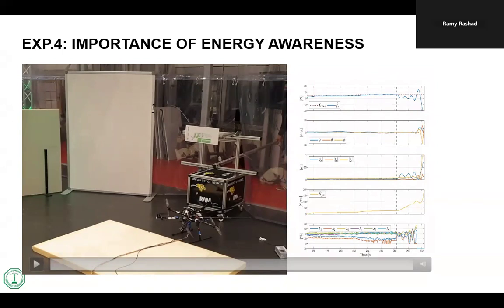So a loss of passivity means here that I'm not guaranteed that if the environment is there, I'm going to be still stable. But what happens if the environment is not there? This is a typical example where you really see that the standard way of thinking about range and pose separately doesn't work. You have to think of them both together. You need to think that there's a relation between both. I need to always make the behavior depend on the relation between both. And this is why just doing passivity doesn't usually work in practice, okay?